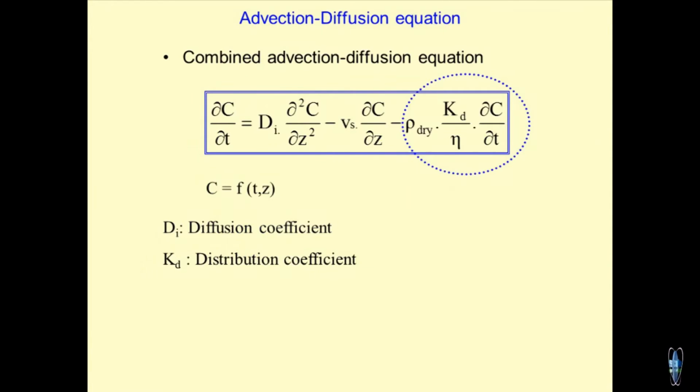Now, if I club all these things together, as a geotechnical engineer, I will be more interested in the advection diffusion equation, because as I said, molecular diffusion, molecular dispersion and hydrodynamic dispersion are ruled out in our context. This is how this equation looks. So, this is a clubbed form of advection and diffusion process. We call this the one dimensional ADE. One dimensional why? Because you are talking in terms of only the Z axis. ADE corresponds to advection diffusion equation.